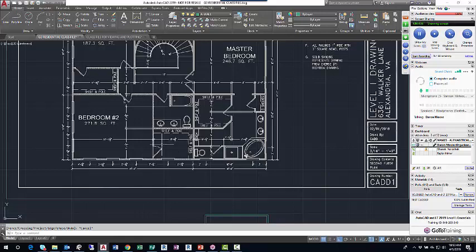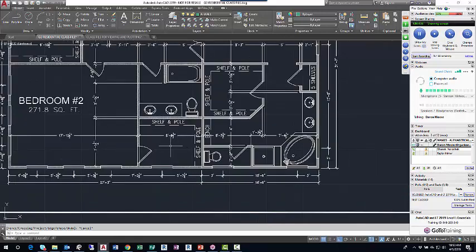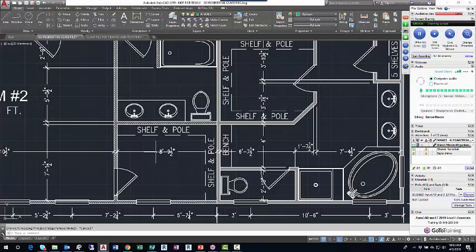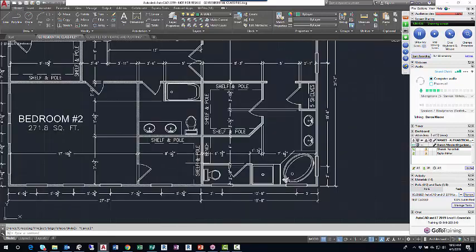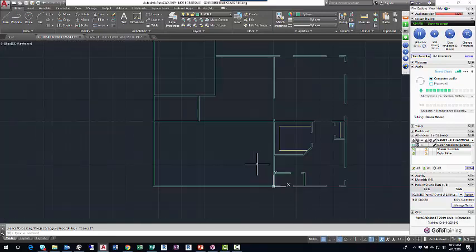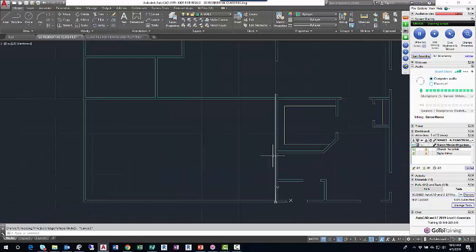The bedroom 3 closet, should be bedroom 2 closet, and the hall bathroom, the inside dimensions are 8 feet 9.5, and I'll just zoom down and I'll just offset that leftmost vertical line of the master bedroom. I'll go offset 8 feet 9.5, enter, left click that leftmost vertical line of the master bedroom, move left and left click, and then all walls are 3.5 inches thick.